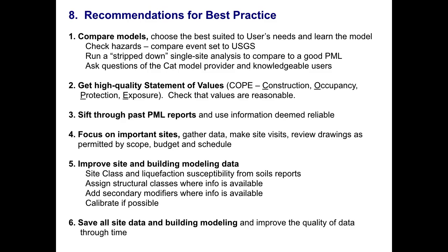We want to improve site and building modeling data, the site class and liquefaction susceptibility from soil reports, assign the appropriate structural classes where information is available to support that, and add those secondary modifiers where the information is available. And if we can calibrate to reliable past reports, then that's a desirable thing too.